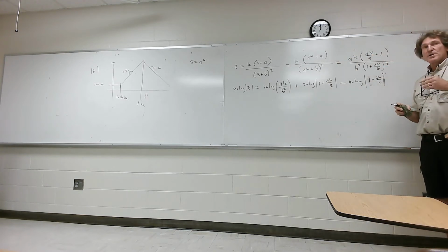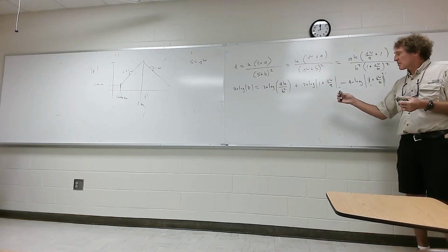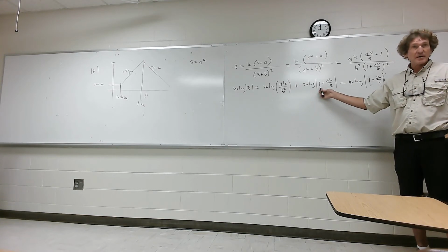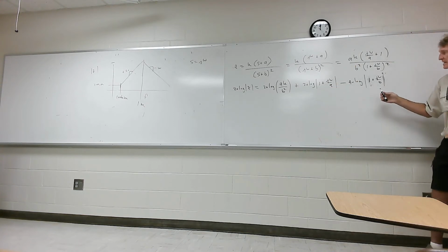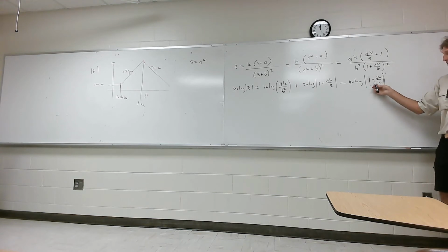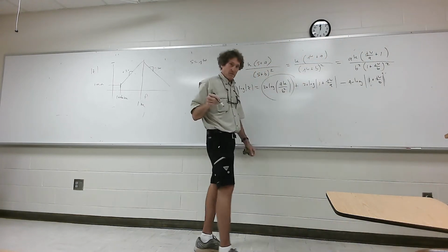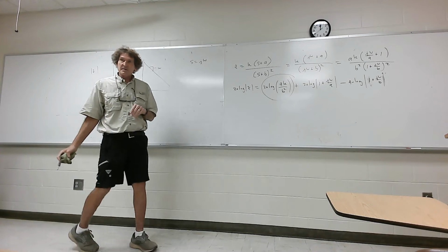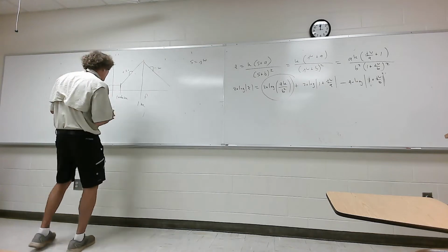Now, when you're at low frequencies, take omega equals 0. Hear me now. When omega is equal to 0, this is what? The log of 1. What is the log of 1? 0. Y'all follow me? So if omega is 0, start at the lowest possible frequency, this term has no effect. When omega is equal to 0 here, it's still log of 1, it's 0 as well. Do y'all follow me? So at very low frequencies, the only thing that happens is this, right there. Okay? Now we're going to equate that in a second to 100 ohms. But hear me out in the whole thing. With me?